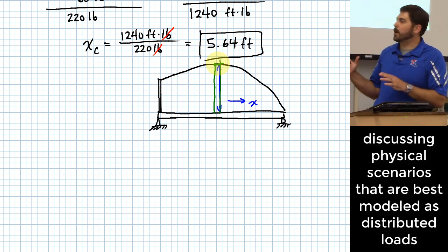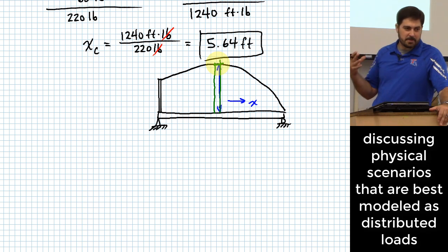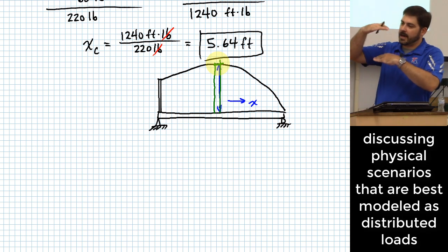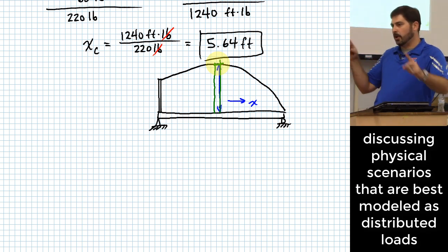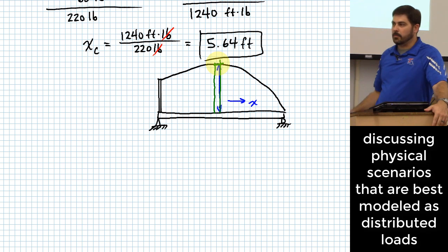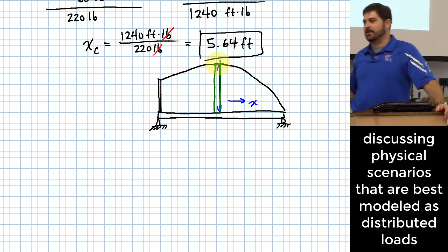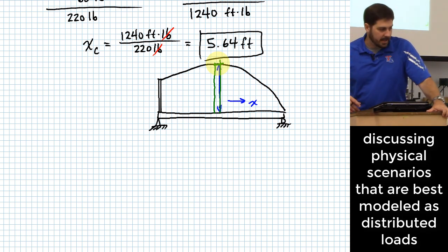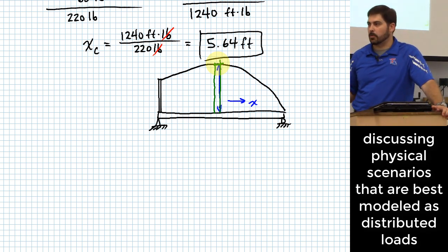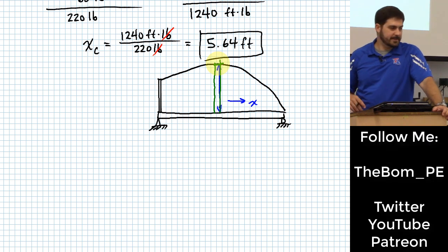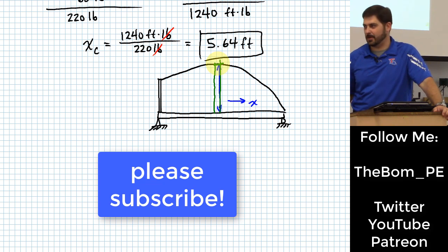So I'm not doing this problem right now, but I'm getting you to think conceptually that this is a place where this kind of thing could arise, if you have the height of a stack of something that's variable over the length of a support. You might need to find the centroid of that pile so that you can figure out where to apply a lumped load and get the reactions at the supports. Okay? Does that scare you? Not trying to scare you, but I want you to have an idea that there are applications where this might matter. All right.